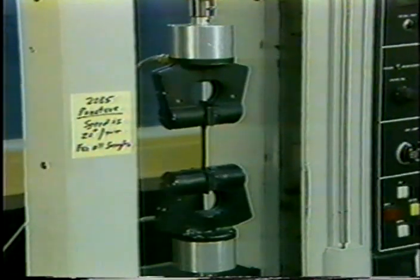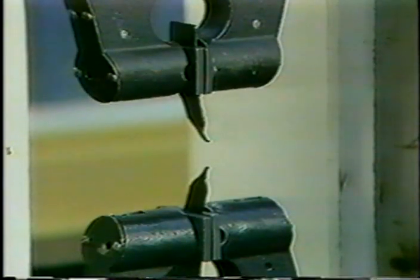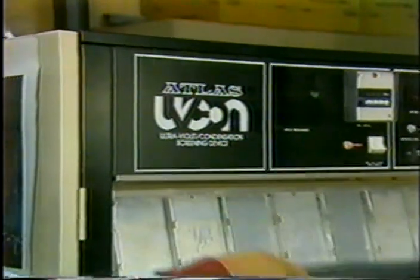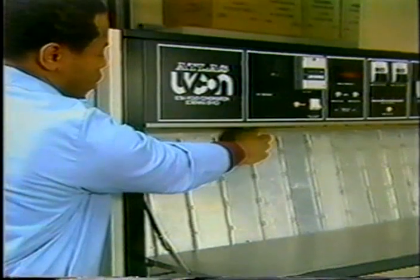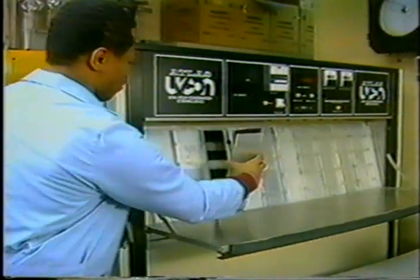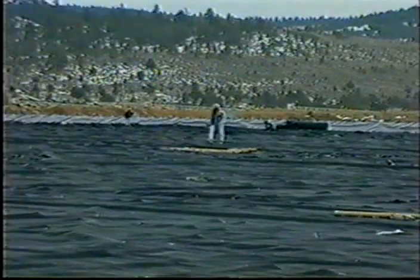This tear test measures the propensity of a geomembrane to tearing once the edge has been nicked, as can happen in handling. The tear test can also be performed on a geomembrane specimen with a special shape. Geomembranes must also resist exposure to ultraviolet light while the landfill is being constructed and until it is capped. As landfills may have a design life of 100 years, liners must be extremely durable.